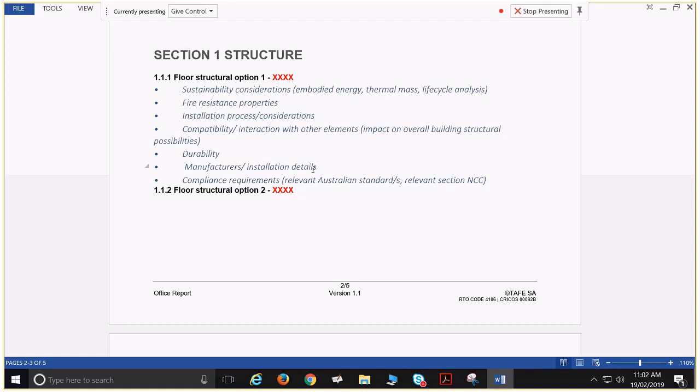We can't just say, all right, let's use concrete for everything, because that might hold up construction for a very long time, as we can't load it for 5 days, etc. We have to think about how these materials go in, and when. Do we have to do the floor before we do the walls? That sort of thing. Potentially, in the real world, we're creating this document for a client building a new home, so it's for someone that doesn't necessarily know, and we're just laying out the options for them.